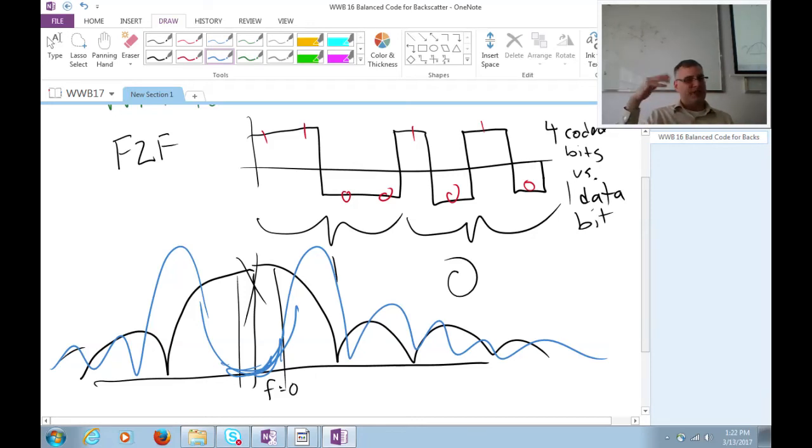Now it turns out that for CMOS logic in particular, but generally in all logic, holding a state between clock cycles takes very little power. Why? Because there's so little leakage current in most of these devices. Only now, when we get down to like 14 nanometers, are we actually seeing that leakage current starting to become a significant factor compared to the current it takes to transition to a state. So once you have a fixed number of devices in a synchronous logic machine, the power consumption winds up being almost exactly proportional to the clock frequency.